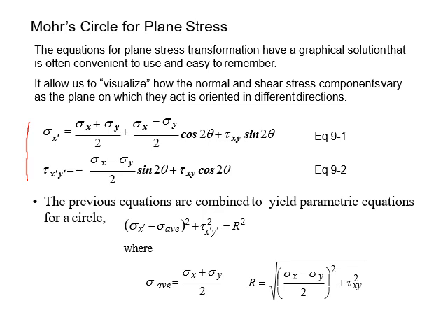After that, we modified the equation to find the principal stresses, or the maximum and minimum normal stresses. We also found an equation to find the maximum shear stress. Basically, this square root at the bottom is the maximum shear stress.